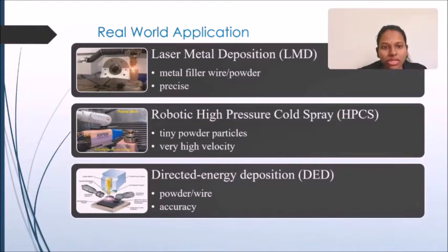One of the reasons for using this LMD process is because it really opens new opportunities, especially for repairing components which are considered non-repairable by the conventional high heat input method. And this method can achieve up to 50 to 70% cost saving compared to the cost of buying a new product.